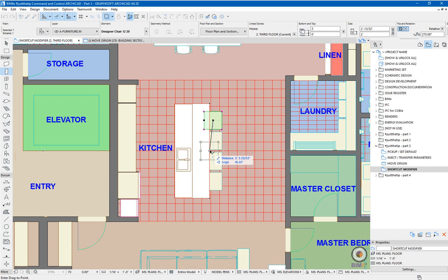And if you're in a particularly busy bit of a drawing, and if you're in a detailing stage and there's lots of things going on, that can actually get in the way of things. So a simple Alt-E suspends that, and you'll see there's now no snapping. Alt-E enables it again, and I can snap and actually put these chairs completely back to back, for example.